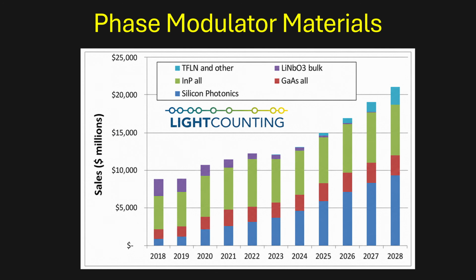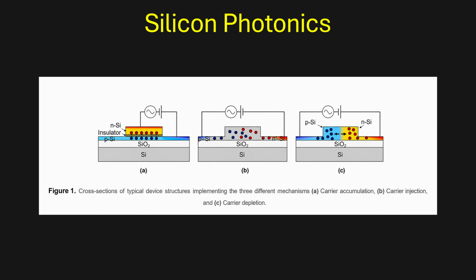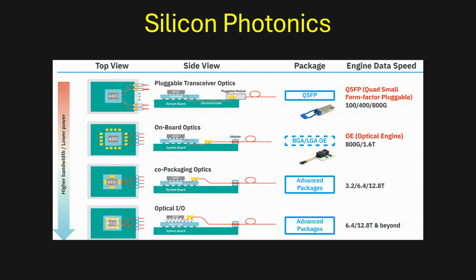Finally, there are silicon photonic phase modulators. Crystalline silicon does not produce a strong Pockels effect or other similar electro-optical effect, so the design usually requires using a p-n junction to change charge carrier density, which then changes the refractive index. Silicon does not have the maximum performance, but it is attractive for manufacturability and for integration with computers in co-packaged optics and data center optical networking.